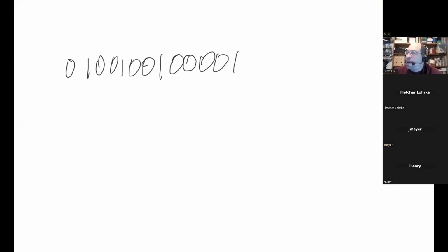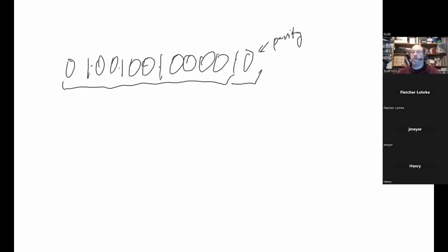You can, for instance, say, okay, well, here's a word, and 1, 2, 3, 4, 5, 6, 7, 8, 9, 10, 11, 12, 13 characters, let's say. Okay, let's count the number of ones. 1, 2, 3, 4. There are 4 ones. That's an even number, so we're going to put a 0 at the end. So this is our parity check. It looks for a comparison of the first 13 bits to tell whether they're even or odd. And then if we get an odd number, that means something was wrong. We made a mistake. So that's the simplest way to do it.